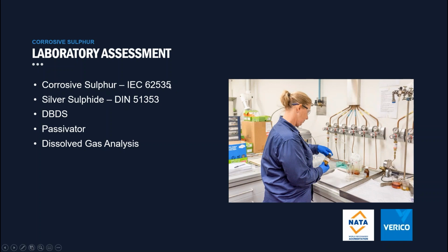So we incubate your oil sample with some copper and kraft paper for 72 hours at 150 degrees Celsius. And if we see very dark tarnishing of the copper and the paper, this tells us that the oil is corrosive. If we give you a positive result in this test, we then recommend that you do additional testing to further understand the extent of the problem.